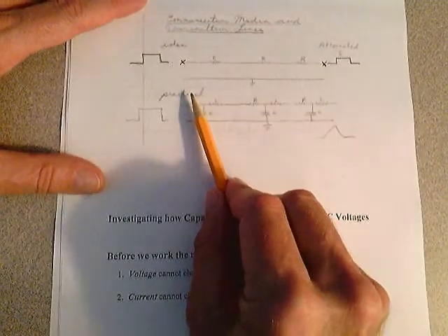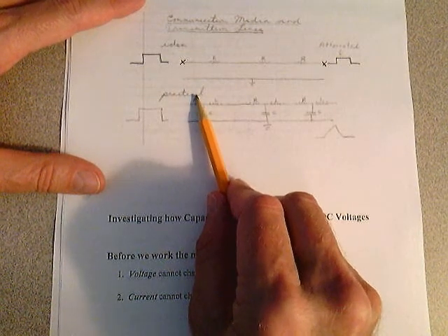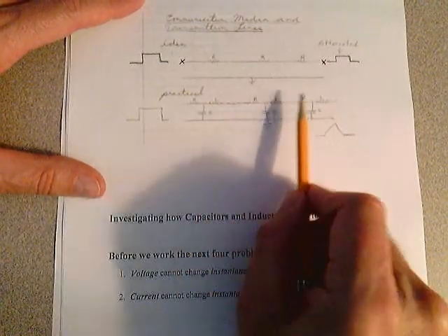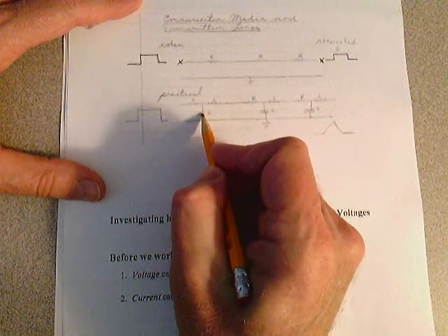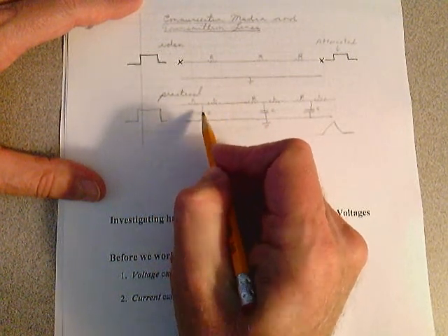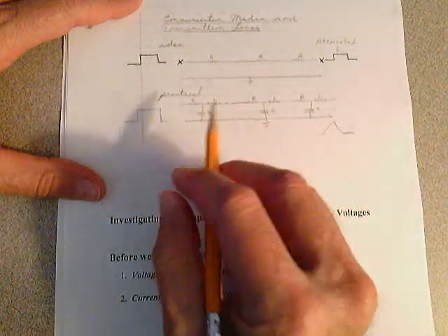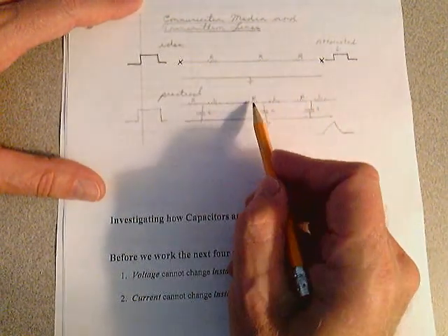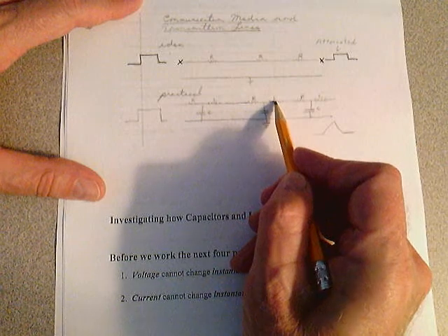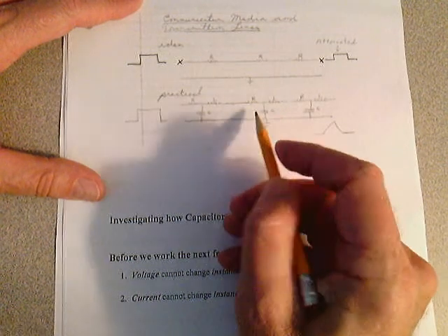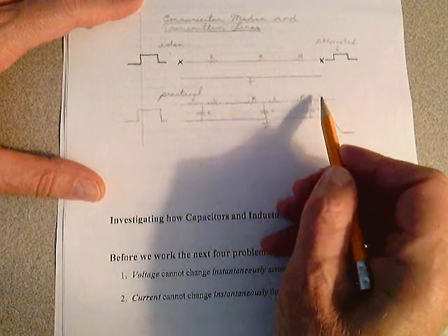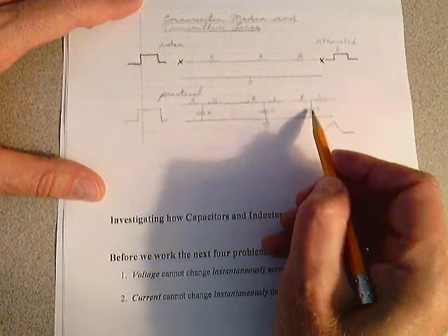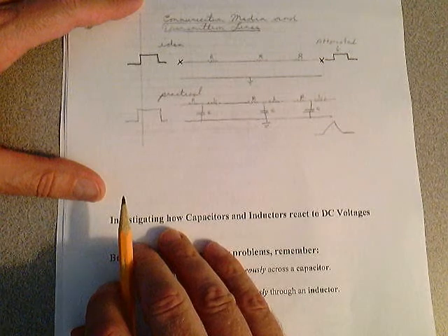Okay, let's look more practically at the circuit in terms of not only these resistances, but you have resistance, you have inductance, and you have this parallel capacitance to ground. And then in the next foot, they model more resistance, same inductance, and same capacitance. And within the next foot, we have series resistance, series inductance, and parallel capacitance.